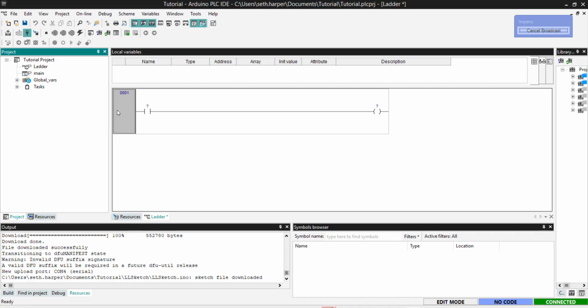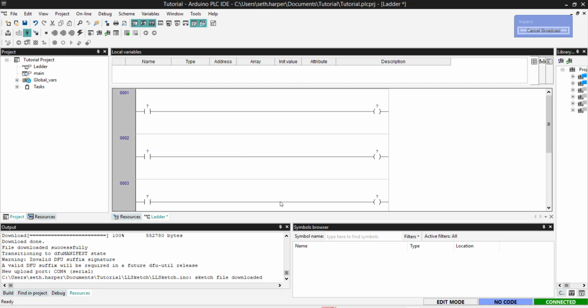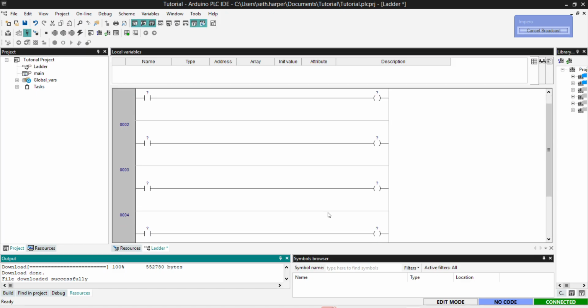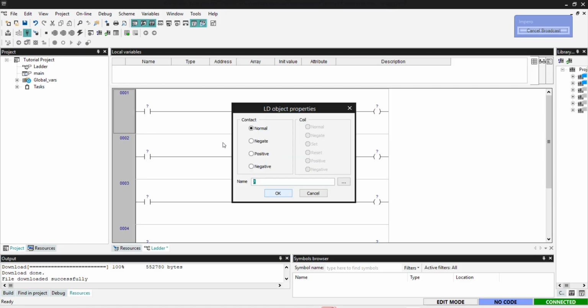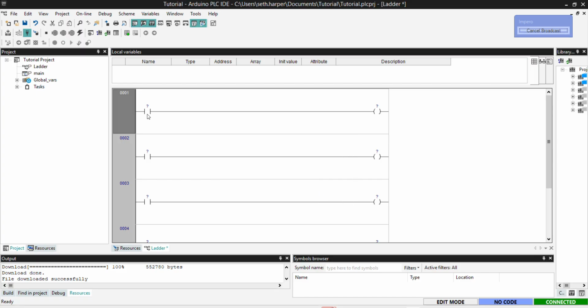All right. Here is the reason that it is called ladder logic. You will see that this resembles something of a ladder. Crazy, right? Okay, so you got rungs on a ladder, right? Inputs are on the left. Okay, this is a normally open contact, which means if this happens, do this. Where this is a coil, which is an output.